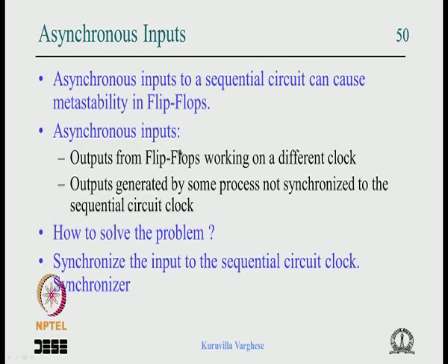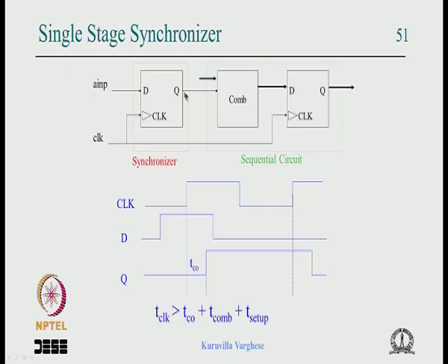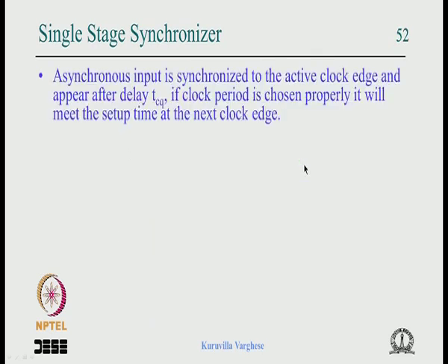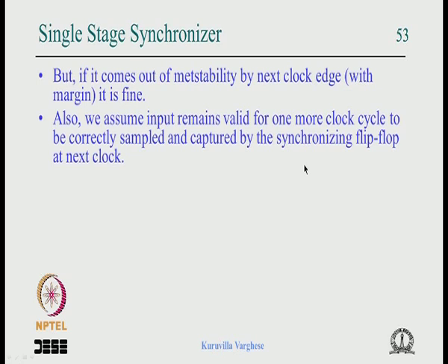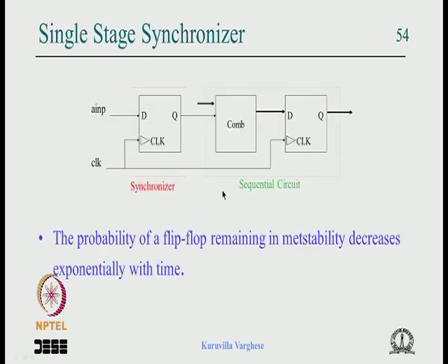But our hope is that if this synchronizing flip flop gets into metastability, by the next clock edge it comes out of it, and if there is enough time for it to propagate through the combinational circuit and meet the setup time at the destination register, it's okay. Okay, so that is the real hope. But I can only make a statement here; we are not going into the analytical part of it.